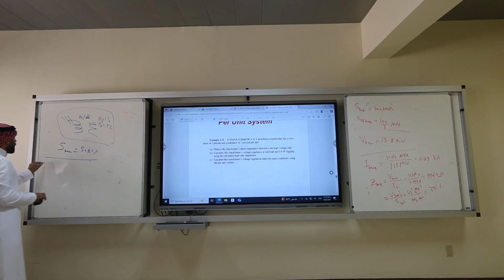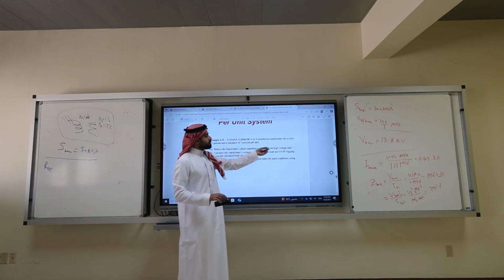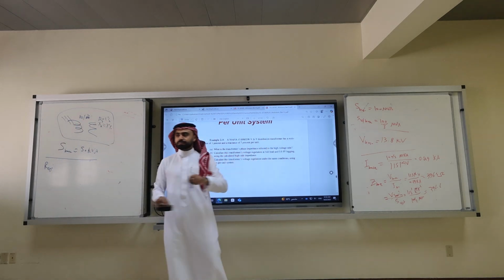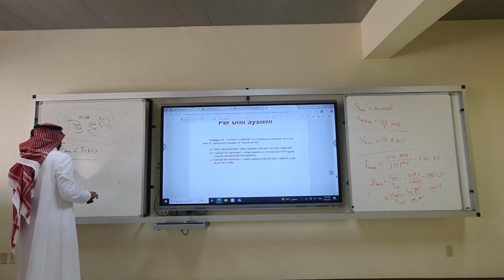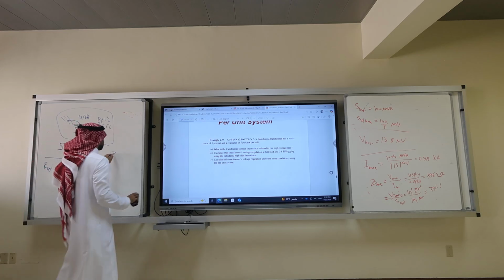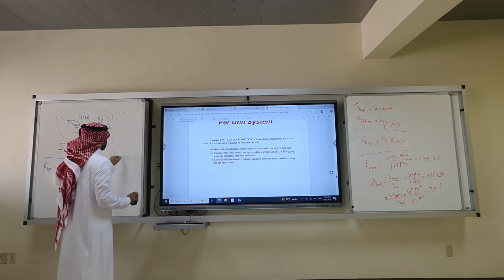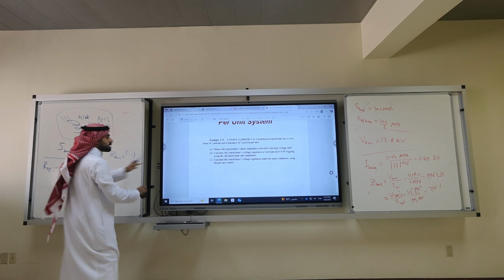So this is S base equals 50 kVA. So what is R equivalent? Let's say referred to primary. What is the transformer phase impedance referred to high voltage or primary? It is 1% times Z base. What is Z base? He said refer everything to primary. 50 over 3. No, what's the equation?